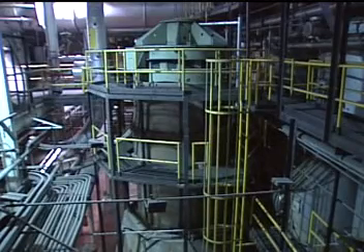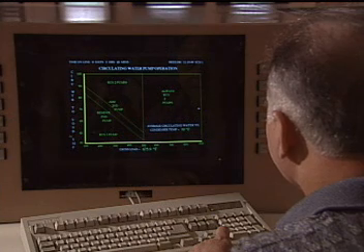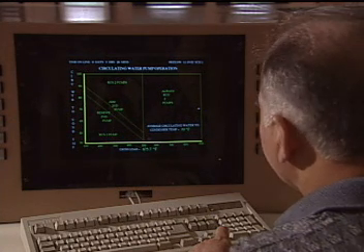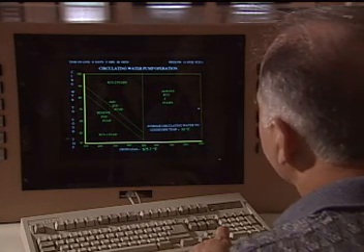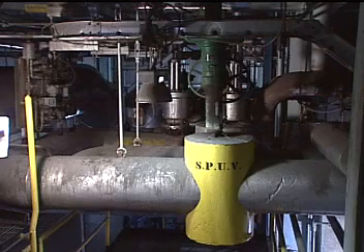Another task that must be performed to prepare the turbine for startup is starting the circulating water system. The circulating water pumps move water through the condenser tubes to prepare the condenser for operation. Many turbines also use gland seal or sealing steam systems. For these turbines, starting the sealing steam system is a necessary part of startup preparations.